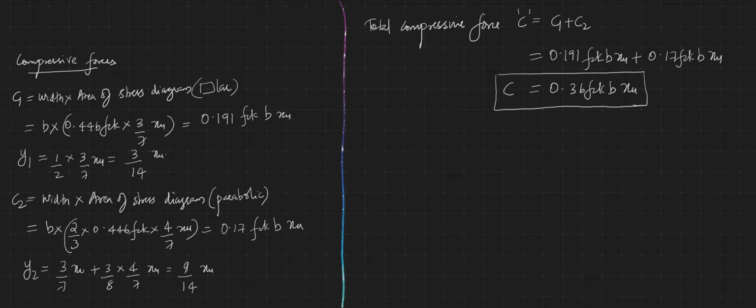And now you need to find the line of action of this force. I will call it y bar. That is the distance of the line of action of the force C from the top compression fiber.